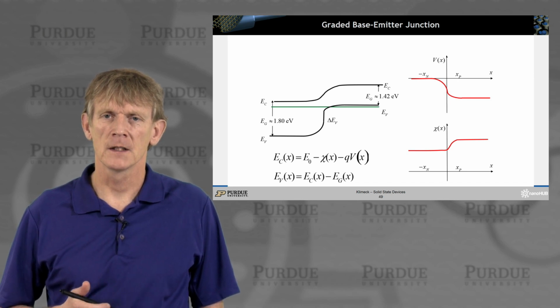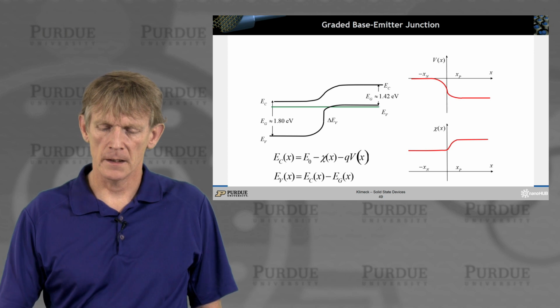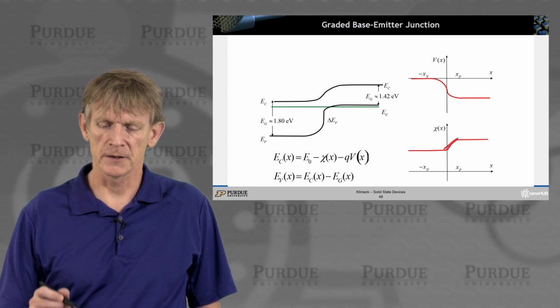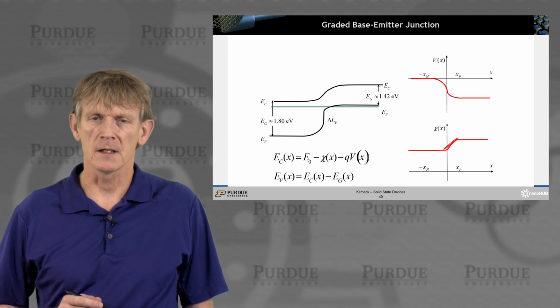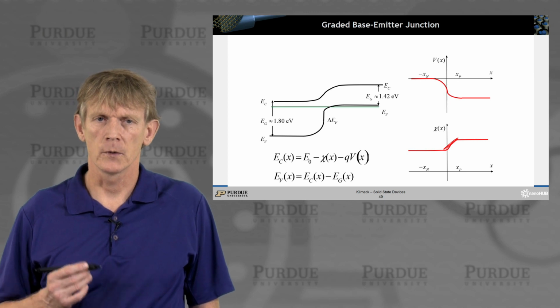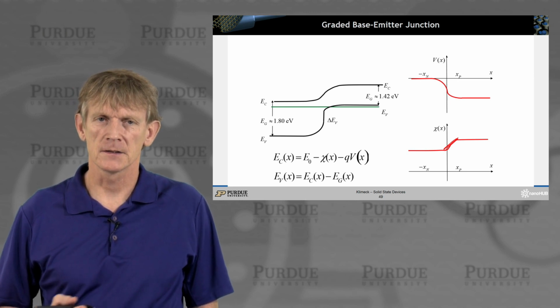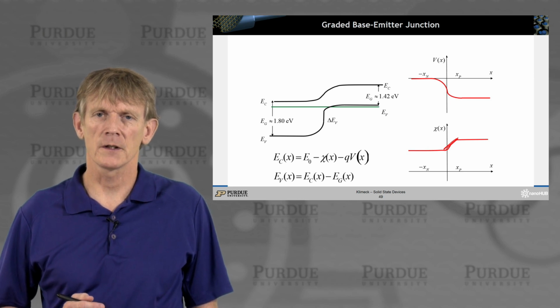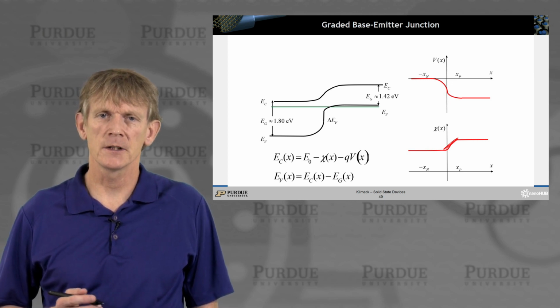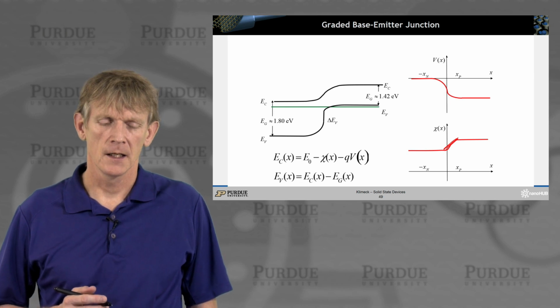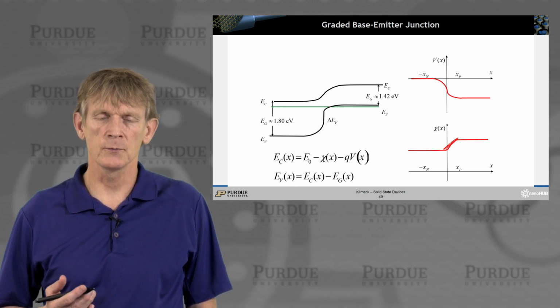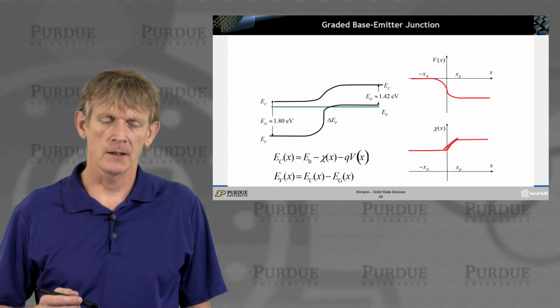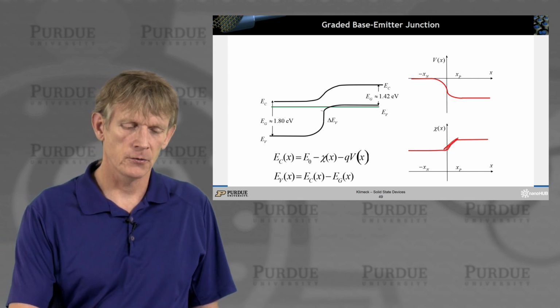Okay, so you have a graded transition for the material, and this would be here on the chi, the electron affinity, across the junction, and you've gotten rid of the spike, okay? And what you see now looks like a really smooth band edge diagram.